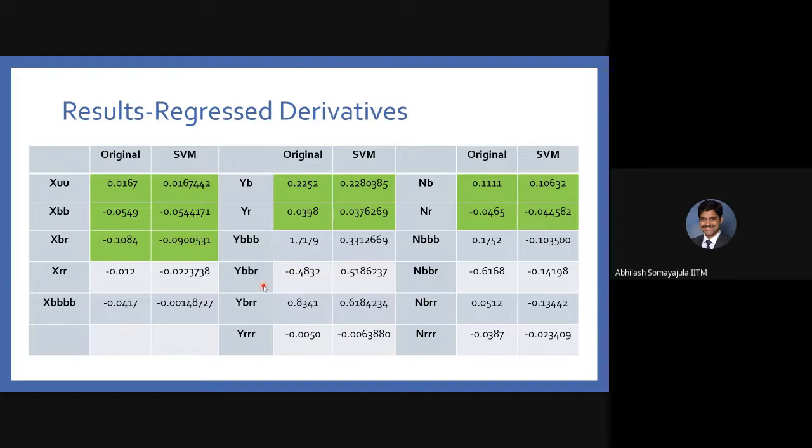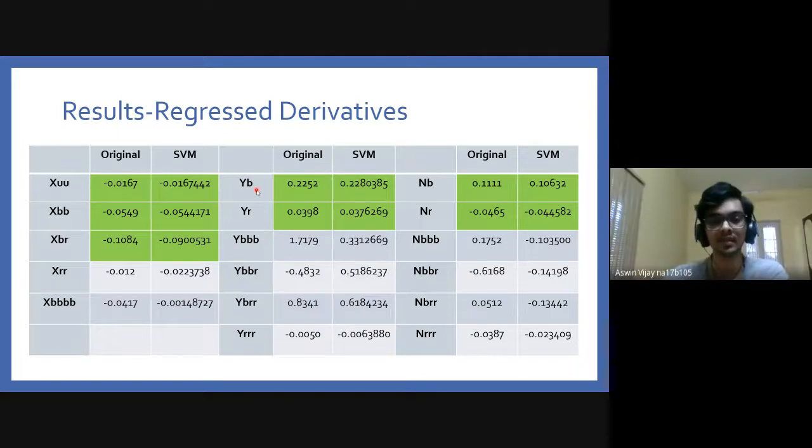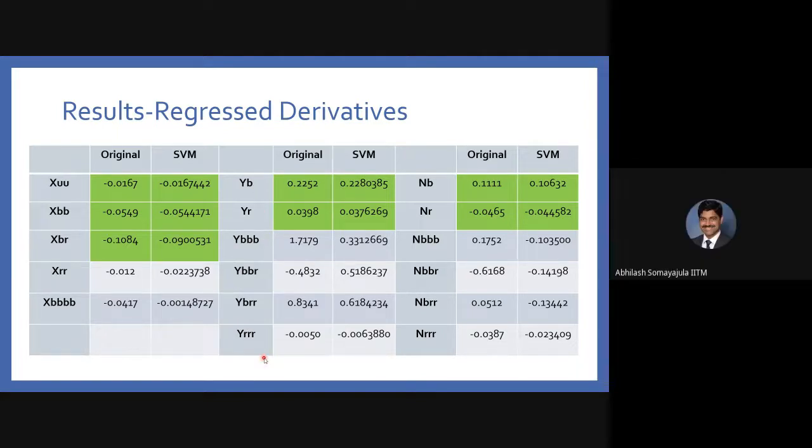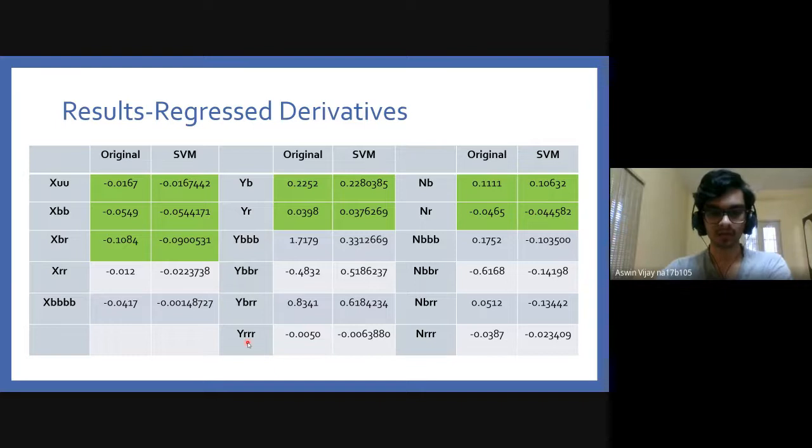If a derivative is not making much of a dent in the dynamics in any sort of maneuvers, then predicting that coefficient is impossible. Only those maneuvers where these coefficients make a significant contribution to the dynamics allow us to try to predict them. So we can't add more terms, we can only get rid of terms right now.